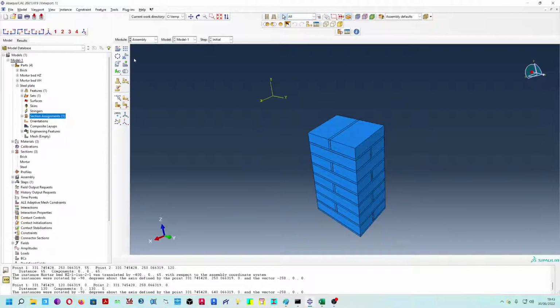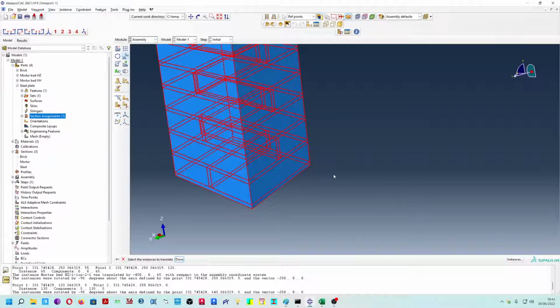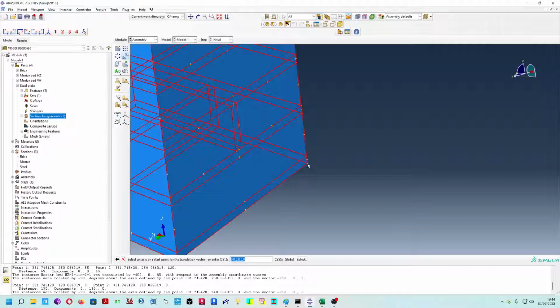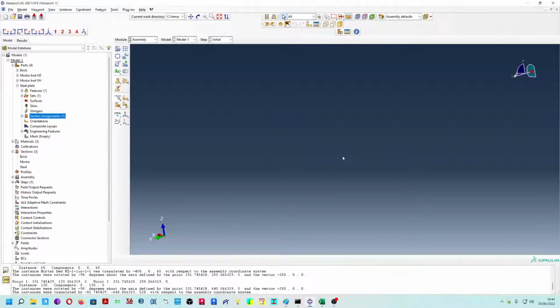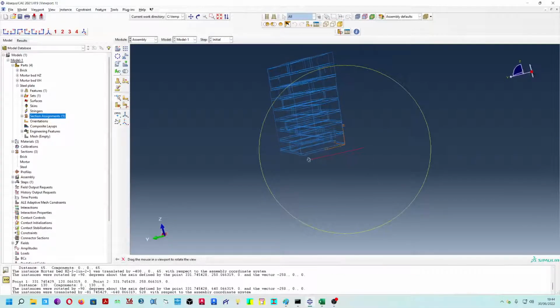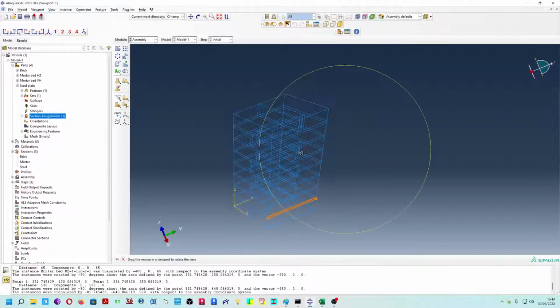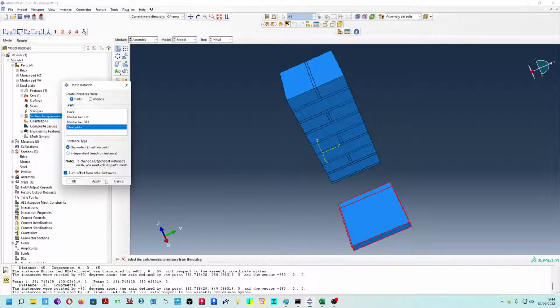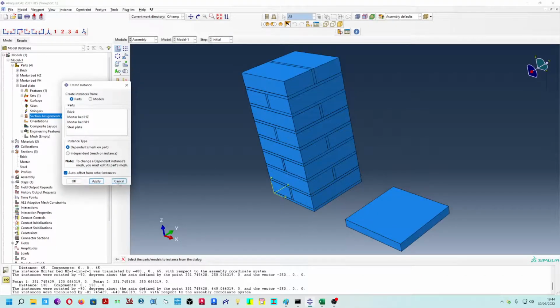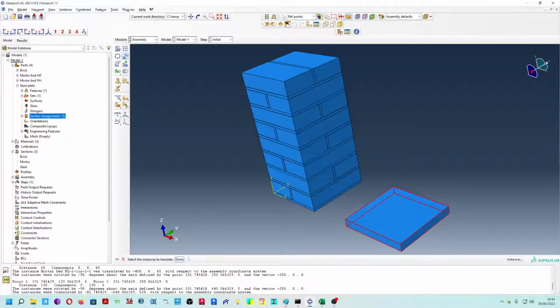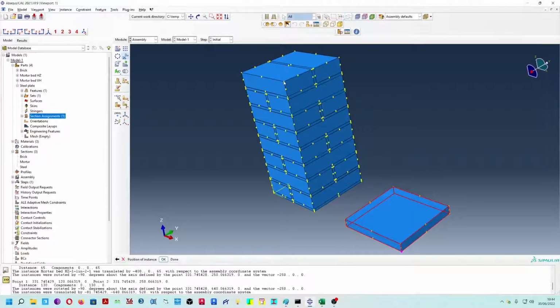Okay, so I would like to move then this to the origin. Translate. Select everything. Done. I click this node and I set 0, 0, 0. Enter. Done. Here we are. So I have to put the plates. Steel plate. Apply. Translate from this point to this point.